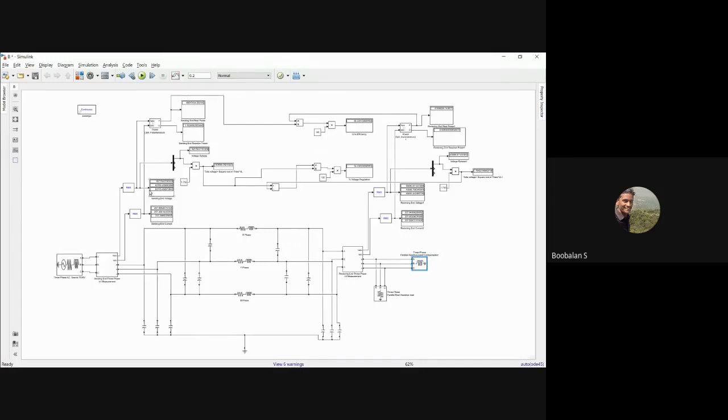Any doubt up to this real power calculation, these things, efficiency calculation, voltage regulation calculation? Anyway, we'll have one more thing we can calculate, apparent power actually. So you can calculate receiving end apparent power and sending end apparent power. These are what we call real power, actually, which we already have. So apparent power we need to calculate. Apparent power will always be a little bit higher than my real power, because my apparent power is in kVA.